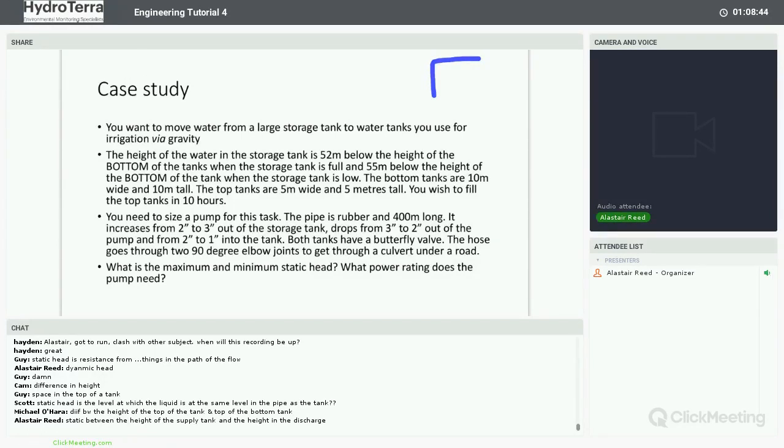So people often go, oh, it's easy to pump, let's talk about wine. We need to move wine into a tank and the tank's 2 meters high. It's easier to pump the wine over the top of the tank rather than push against the pressure of the wine from the bottom valve. Well, actually, it makes no difference because the pressure has to be overcome whether it's forced into the bottom of the tank or has to go up against gravity over the top of the tank. It only matters where the height of that liquid is.